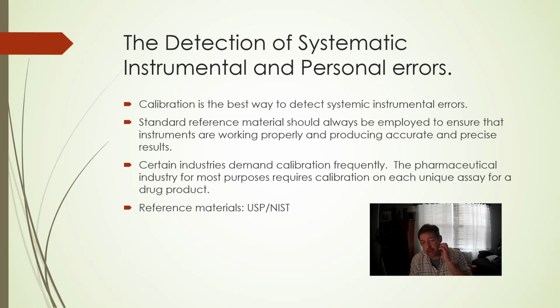Certain industries demand frequent calibration. Again, the pharmaceutical industry, which is where I mostly come from, for most purposes, they want you calibrated on each unique assay you're doing for a drug product, and they want you to use a USP reference material. And there's a whole process called method validation that I'll get into on another video one day. And accuracy and precision are two things you have to address when you're validating your method.